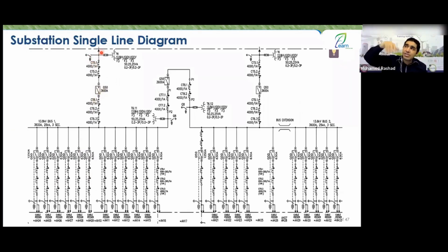In the previous stage, you had voltages like 33 kV, 115 kV, 110 kV, 130 kV, or 380 kV, and there was a transformer. This transformer stepped down the voltage from the normal level to what level? To the low level, the medium level, which is the medium voltage, and brought it here to your feeder. So this feeder is considered for you as what? A transformer incomer. And all the outgoing ones are circuit breakers.